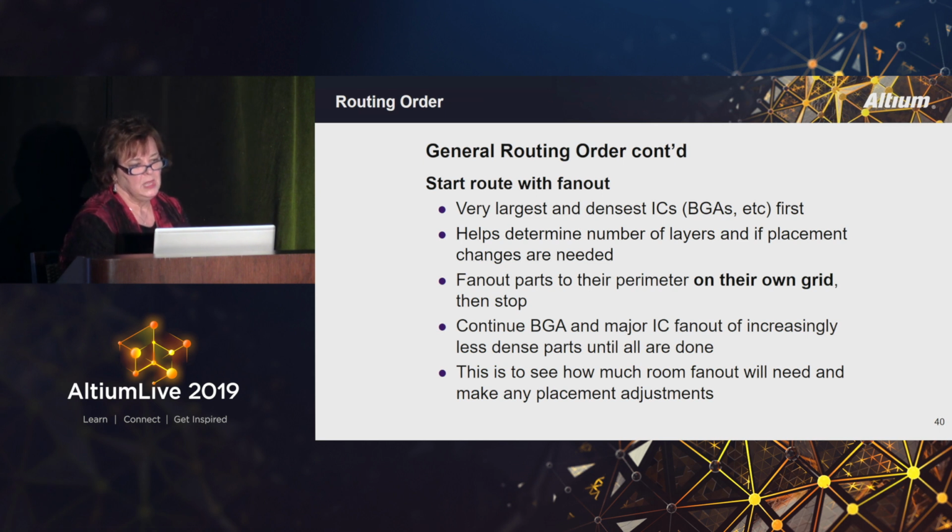And then continue routing the BGA and any ICs, fan out increasingly dense parts, and this is done to see how many placement adjustments you may have to make.